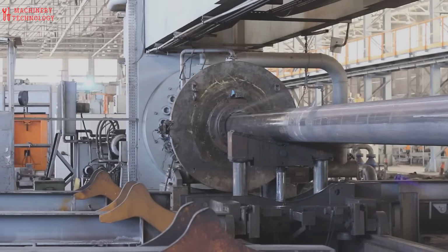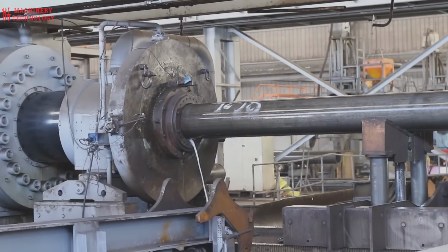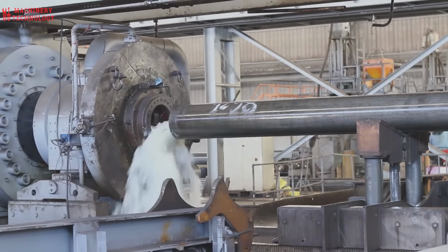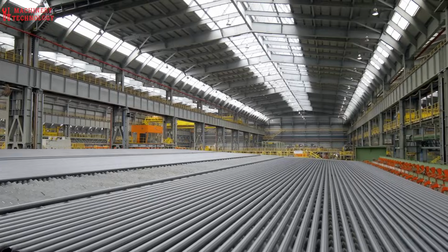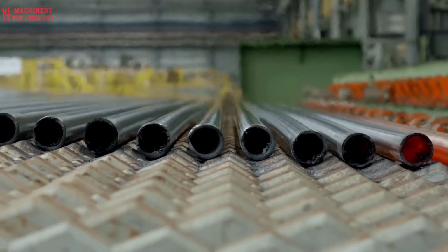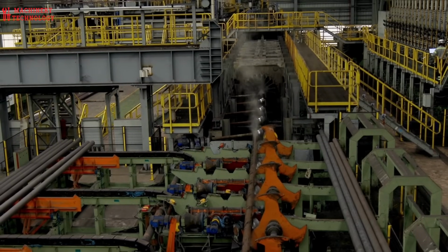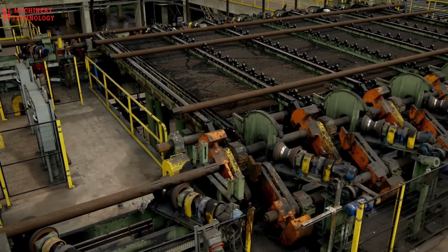Manufacturing steel tubes. There are three main methods of manufacturing tubing that lend their names to tubing classifications. Seamless. Seamless steel tubes are produced through extrusion. Extruded tubes can be formed in a hot or cold process. Long sections of steel bar are forced through a die that blocks out the intended shape of the tube.